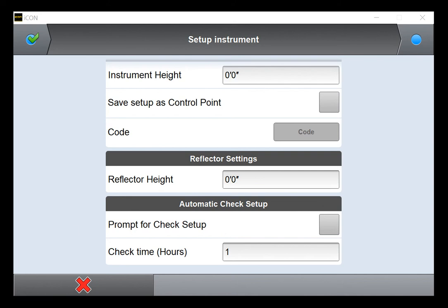A few examples of these factors are vibrations in the deck, the crane turning with a load, the crane setting loads on the deck, high-rise buildings leaning towards the sun, heavy wind, people working near the total station, and human error. At this point, it's important to mention that if you notice a high volume of people working near your setup, you need to pay special attention to your total station. Even if it's set up on a deckmate or column clamp pod, which ensures it won't get knocked over, it can still be knocked out of level.